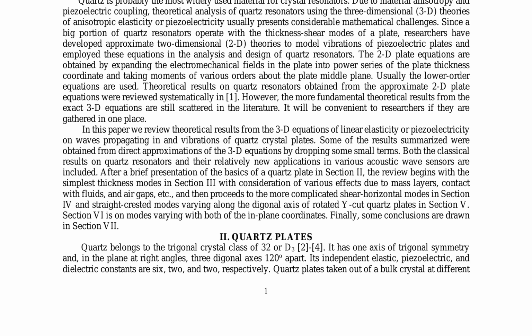The analysis incorporates effects due to electrodes, mass loading, contact with fluids, and air gaps, as well as the behavior of shear horizontal and straight-crested modes. This in-depth review is foundational for understanding and designing quartz crystal plate resonators and sensors.